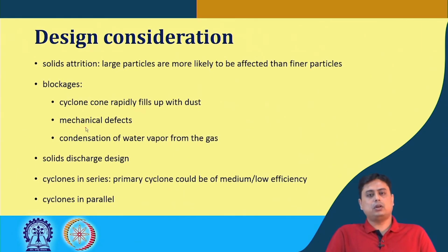There are chances of solid attrition. In fact, particle breakage can happen, and this happens logically more in the case of larger particles. The particles impact each other, so particle breakage happens, but how it influences the performance is still in the research category. But logically, larger particles are more likely to be affected than the finer particles.